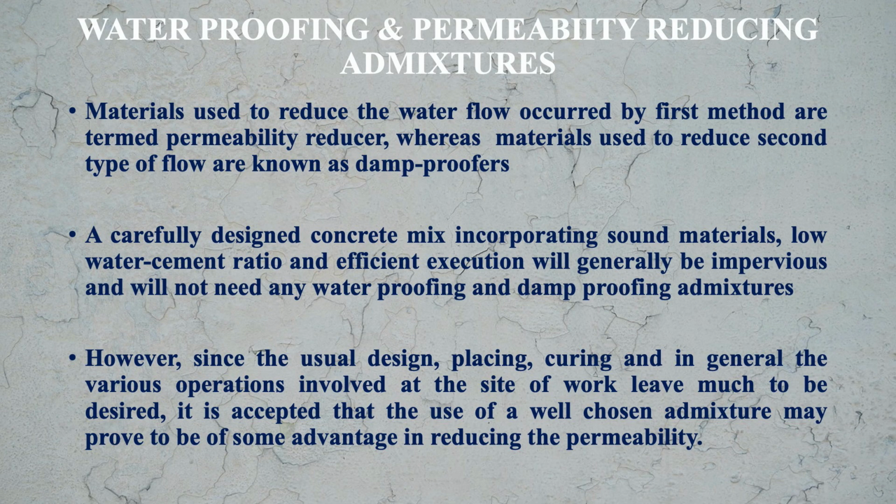However, since the usual design, placing, curing, and in general the various operations involved at the site of work leave much to be desired, it is accepted that the use of a well chosen admixture may prove to be of some advantage in reducing permeability.